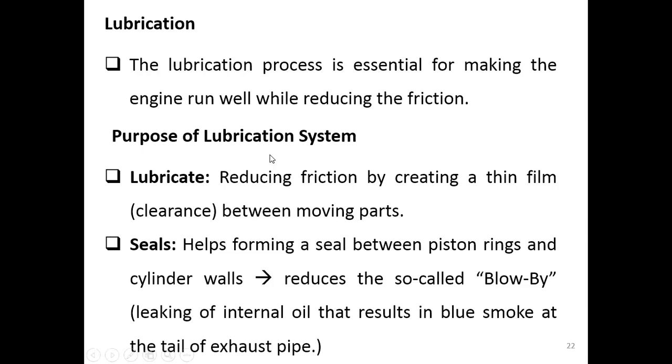The first one, of course, is to lubricate, in order to reduce the friction by having a thin film in the clearance area between the moving parts, which is the surface of the piston and the surface of the cylinder. This is where the friction mostly happens. So reducing the friction in this area is the first purpose.